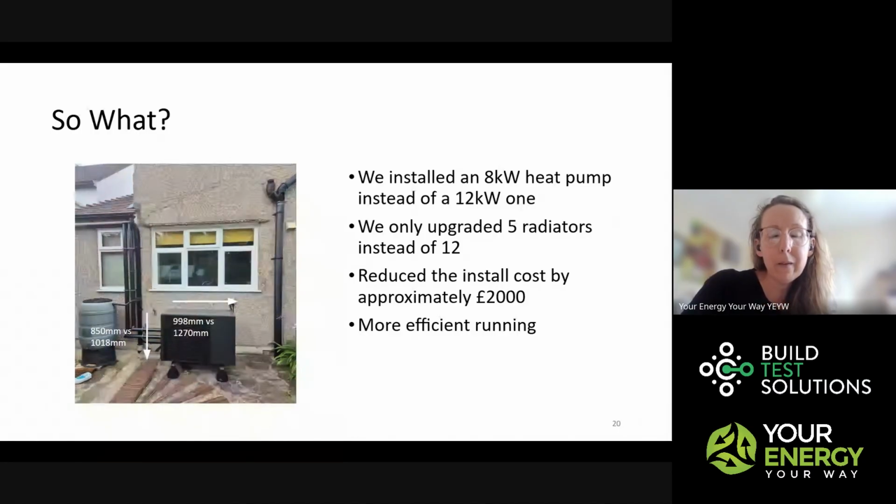I think for me, the biggest impact here was really about the radiators. So in this house, in the end, we only upgraded 5 radiators in the property instead of the 12 that we would have needed to upgrade based on the 12 kilowatts worth of heat loss. So roughly, given the different size of heat pump and given the radiator install costs, I would say we reduced the cost of that installation by at least £2,000, if not a little bit more.